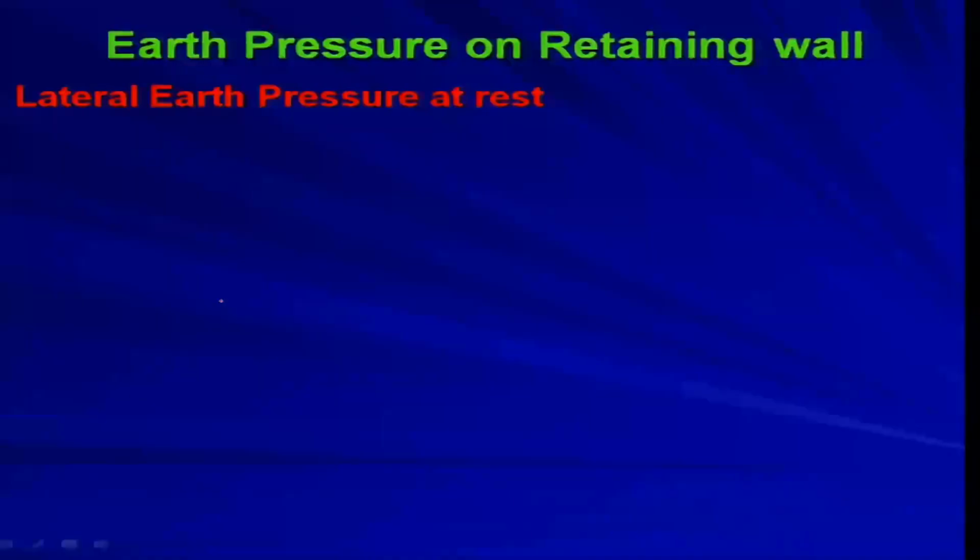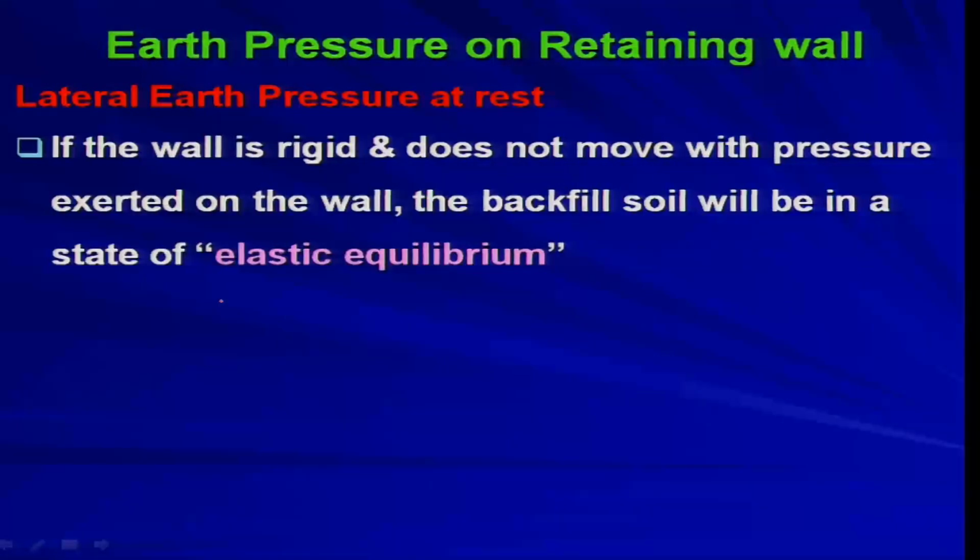Now in this lecture we will be talking about the elastic equilibrium and we will try to establish the expression for earth pressure at rest and earth pressure at active and passive condition. If the wall is rigid and does not move with pressure exerted on the wall, the backfill soil will be in state of elastic equilibrium. That means, when the wall is not moving at all, when the backfill is at rest condition, at that time the soil will be under elastic equilibrium.